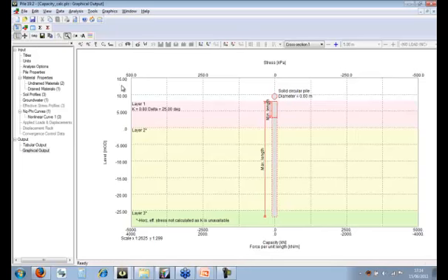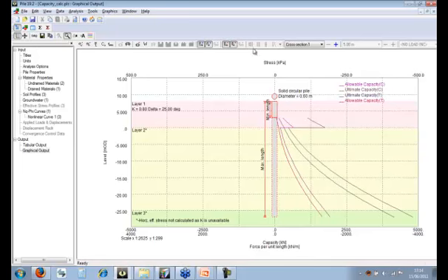But I've just chosen a standard CFA pile. So we've got the total skin friction here and the end bearing capacity. So they come out on the right hand side because they're your outputs. And if we click that off, we can get, for example, the working load and the ultimate load. This is in compression, and again, we can get it in tension. So that gives you an idea of what's going on.